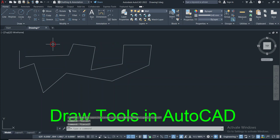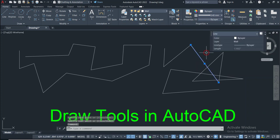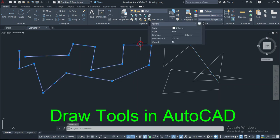In the case of a line, when you draw different segments like this, and this one, and then press enter, when you want to select only this segment and you click, only this segment will be selected. But in the case of the polyline, when you want to select this segment only and you click on it, all of the object will be selected. So this is the main difference between the line and polyline.